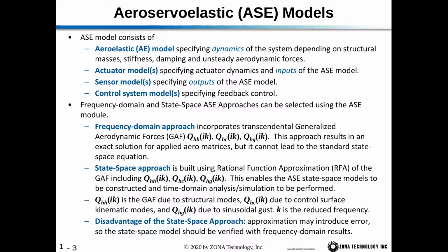The frequency domain and the state space ASE approaches can be selected using the ASE module. The frequency domain approach incorporates the transcendental generalized aerodynamic forces, the GAFs, QHH, QHC, and QHG. These are all discrete matrices which are functions of IK, the reduced frequency.